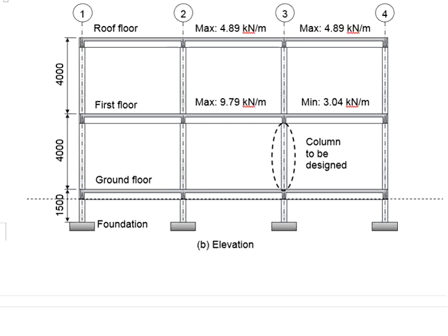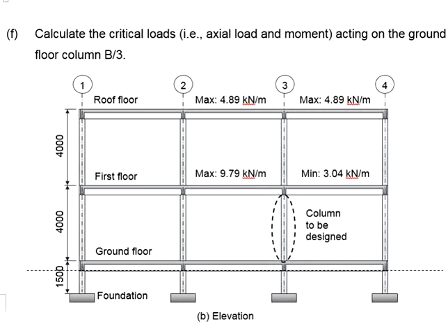In order to acquire the critical moment, we will need to make one beam carry the maximum load, whereas the other beam carries the minimum load. The longer span beam will have the maximum load, and the shorter span beam will have the minimum load. This shall be the load arrangement in order to get the moment here. Now, if you wish to get the moment here, you will do the same. Maximum load at the longer span and minimum load at the shorter span.